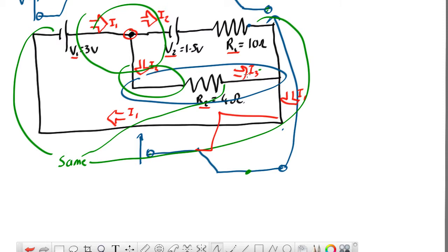Okay, so now the next step is usually to have a quick estimate of what sort of values we're going to get. We've got voltages of a few volts, resistances of a few ohms, so that means currents are going to be of order a few amps. So it might be 0.5 or 2 or something like that. This estimate is a way of checking our answer. It means we know we're expecting currents of a few amps, and if in the end we stuff up the algebra and get a current of 1,000,000 amps or 10 to the minus 5, we know we're wrong.